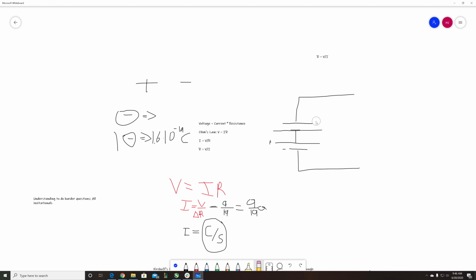So if it was like this, with the short end on this side, negative, and positive on this end, you need to understand that these batteries subtract their voltage. To find the total voltage of the circuit, when I mentioned delta V, you need to figure out that these batteries actually subtract from each other because there's direction in the circuit. That's a key part to understanding. So say this was 9 volts, and this was 5 volts.